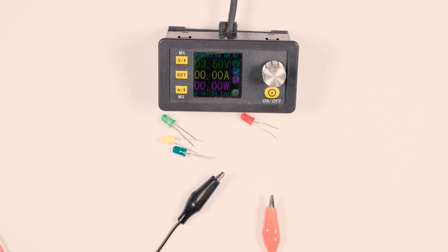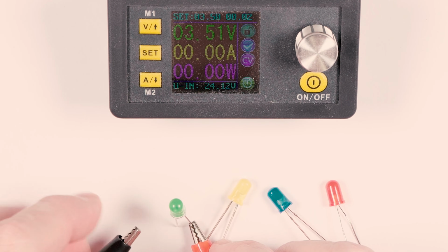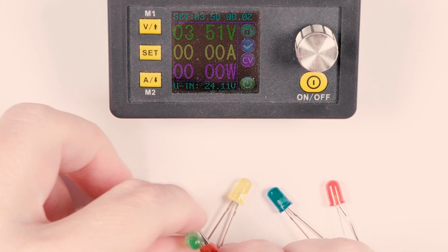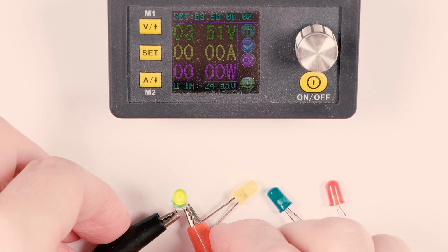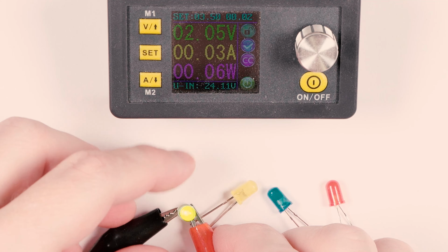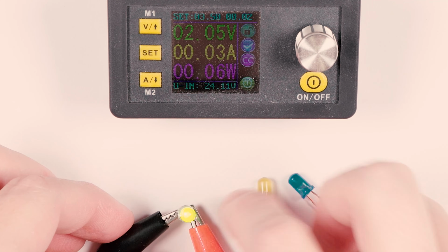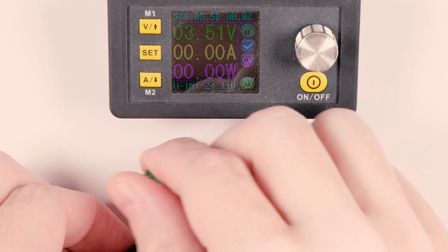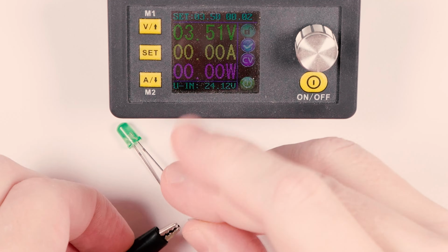Indeed, it is convenient to power LEDs by setting a current limit rather than by supplying a specific voltage. The easiest way to do it, as you probably know, is to connect a resistor in series. That's why they call it current limiting. However, this does not mean that there is no specific voltage for each LED from which it can be powered without the help of a resistor.